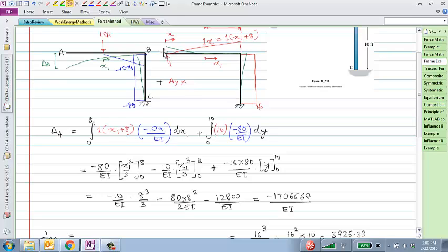We have set up the bending moment diagram for that, but we have not yet actually found it. Okay, so yeah, we can use again the virtual work method. So if I apply the virtual work method to find the displacement at A due to a unit load at A, in this particular case, it's great because the real system is right here, for which we have already found the bending moment diagram. And what's the virtual system? The virtual system is exactly the same thing, right? So the real and virtual system are both right here.